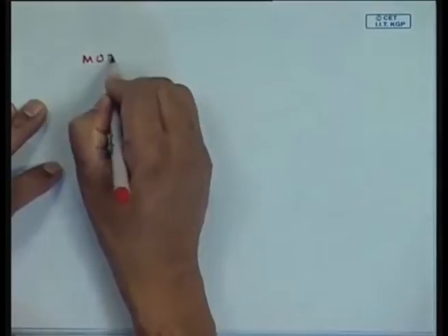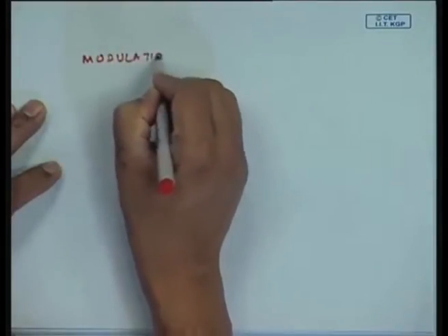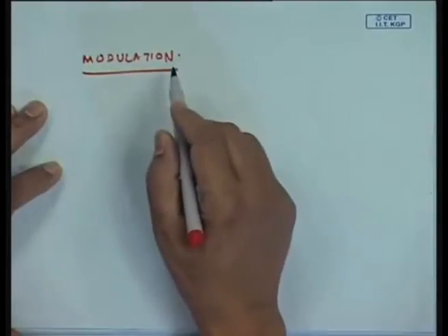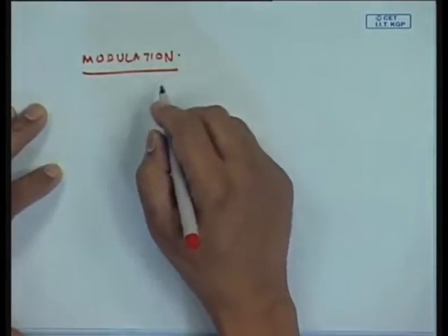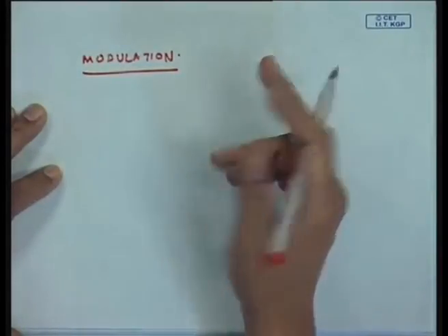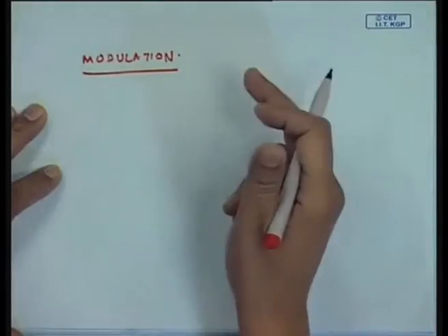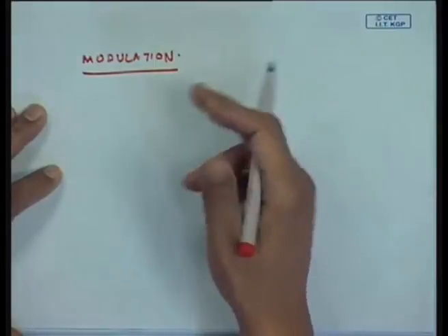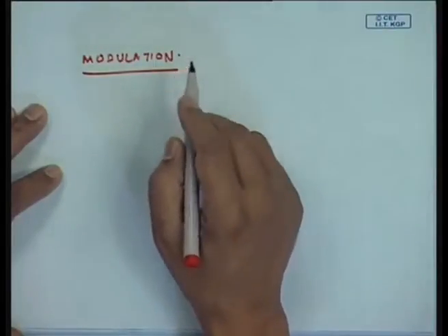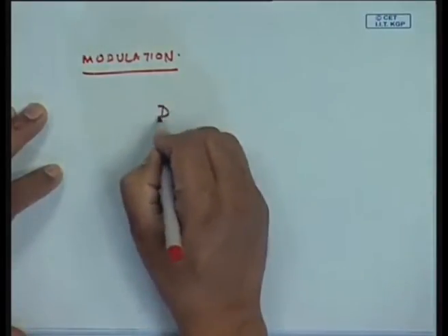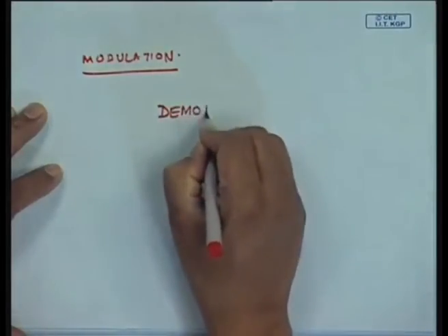So, this happens because of signal modulation. At the generation point of the signal, there is a modulation effect happening because of the frequency of one being related to the other, or one being caused by the other, like the case of the rotating fans which I was telling you about. So, our signal has got modulated, it has come to us as a modulated signal. So, our objective now is to demodulate the signal.